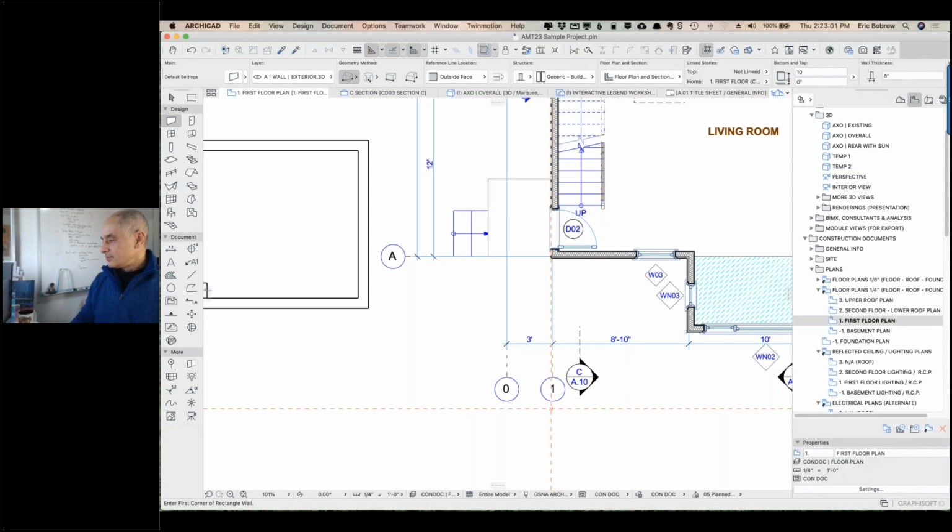All right. So Marek Krukowski says, some worksheets like legends. So I'm not quite sure. I think you may be referring to the ARCHICAD layer. So, talking not generically, but just sort of generally, a worksheet is a 2D working area that you can draw things that you need. You can bring in PDFs or DWG files, etc.